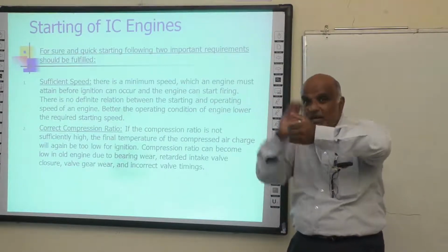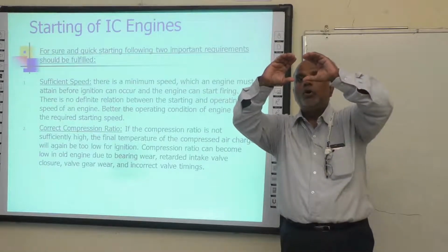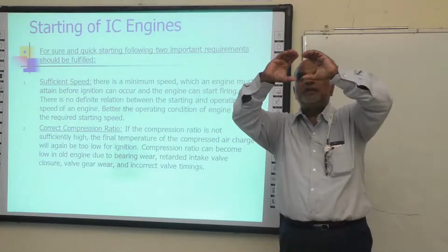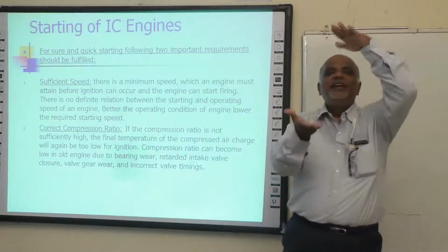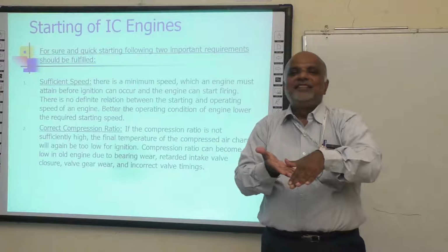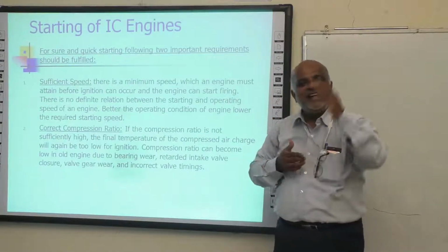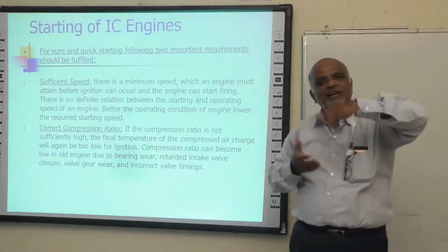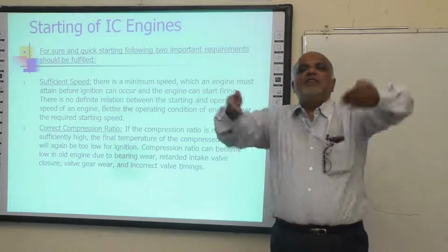The compression space becomes more, so the compression ratio is lower. That's why in a brand new engine, starting is very easy. As the engine becomes older, because of this wear, the starting takes a little longer time.